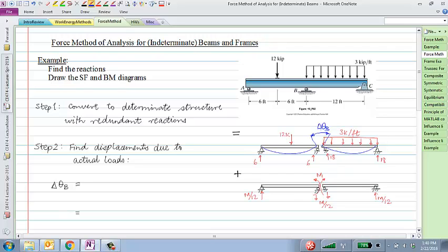Okay. Now, in the same way, I'm going to draw the deflected shape due to the redundant moment. So the redundant moment deflected shape might also look something like that. And if I draw the cross sections, once again, those cross sections would look something like that. And the angle between them, I'm calling delta theta B prime. So the compatibility equation simply is that delta theta B plus delta theta B prime should be equal to 0, right? So the amount of this rotation would depend upon this moment. And the idea, of course, is that I need to apply the right amount of moment so that I close the rotation back together for both those beams and they behave like a continuous beam. Make sense?